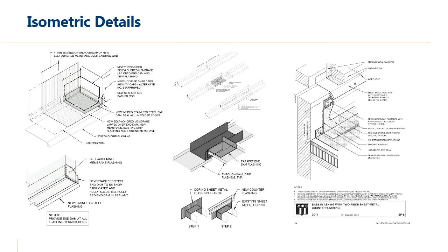But often at these corners and intersections, the issues are a bit more complicated, and you might need to go to an isometric detail. Here are a few examples of isometric details. Some of them show a build of the material, so sequencing of how it's done, and that can be done either by showing several steps, or we have a cutaway type isometric on the right that shows the build in one image by simply showing different pieces as they're installed.